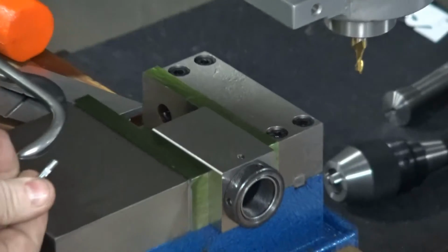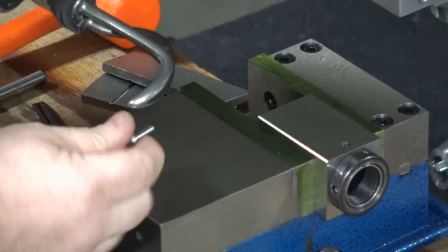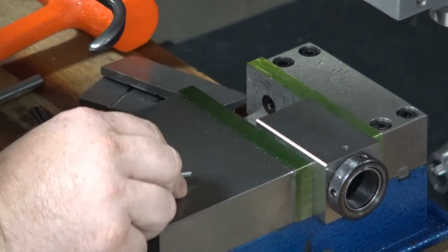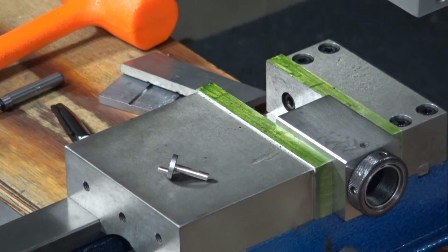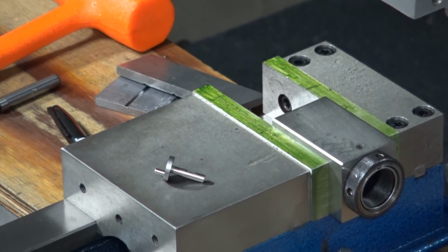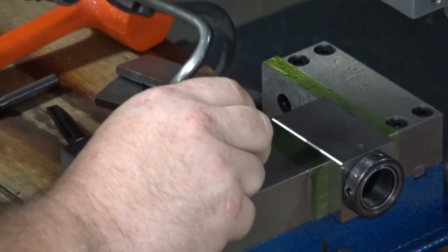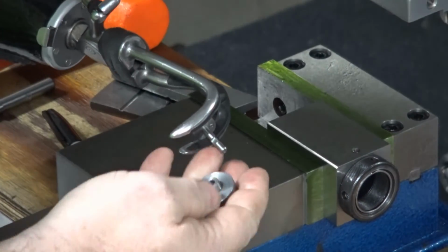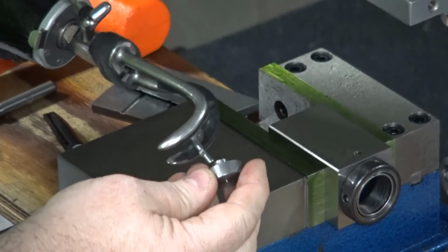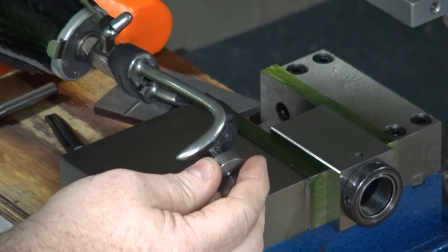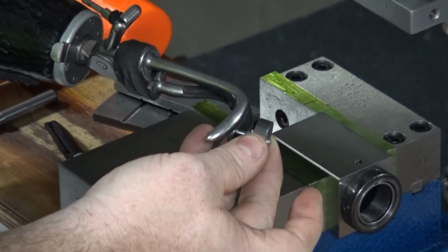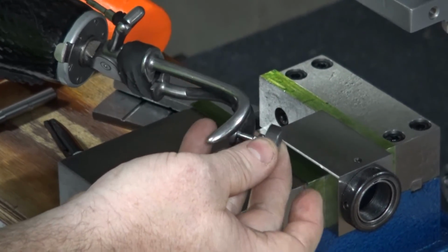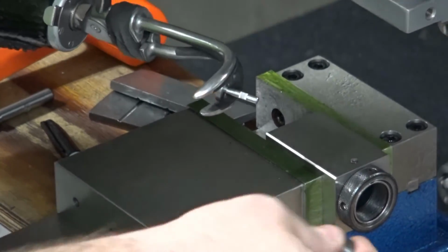There's my crankshaft. There's my flat. So that part, at that stage, is completely finished. We're actually ready to assemble this. For inspection, you can take your flywheel and slide it down over. See how nice that slides over? As long as it slides up and down real nice, that thing's ready to assemble.